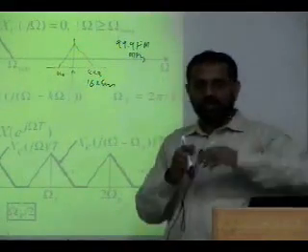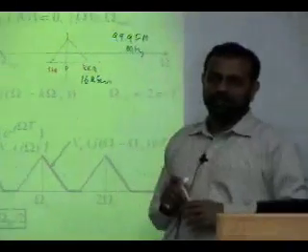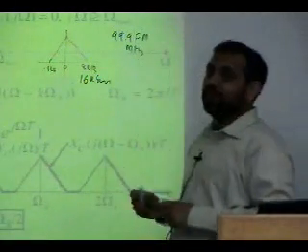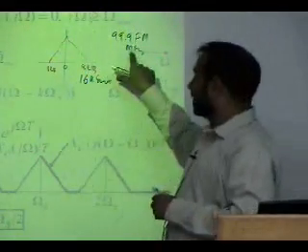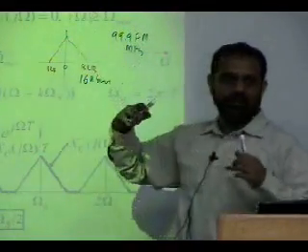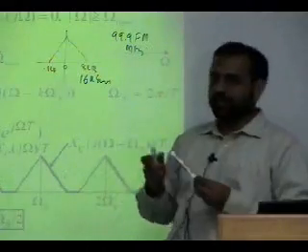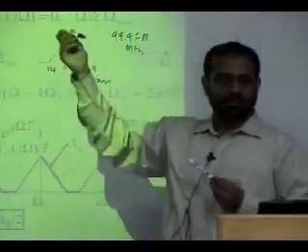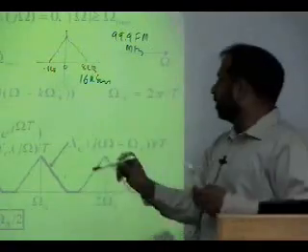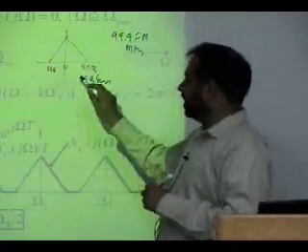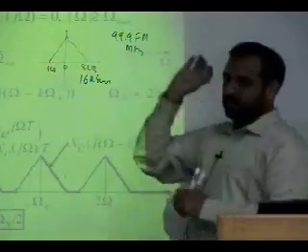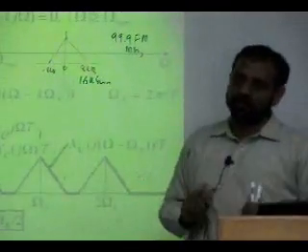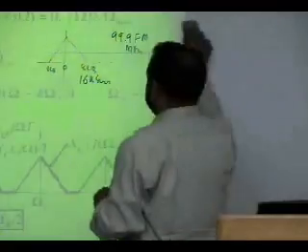So once a signal hits your antenna, you got to sample at a very, very high rate, because it's a high frequency signal. At least 200, as I am saying, approximately 200 mega samples. And then throughout your system, digitally you have to bring it down to this. And at the transmitter you take this and digitally bring it up to this to actually transmit, if you want to do it digitally. So you are not really losing anything.